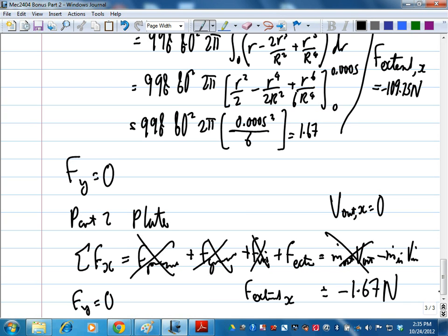Right? If you didn't catch what I just said, these two are the same. M dot V out leaving the jet is the same as M dot V in hitting the plane. You assume that the flow velocity doesn't change, the speed doesn't slow down or anything like that. So whatever leaves the jet, M dot V out, must enter this one. You can do the same integration again, by all means. You get the same.